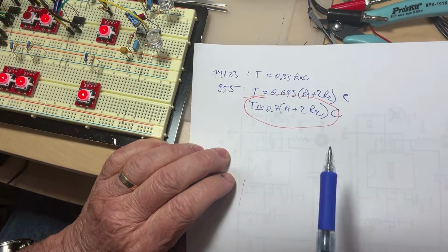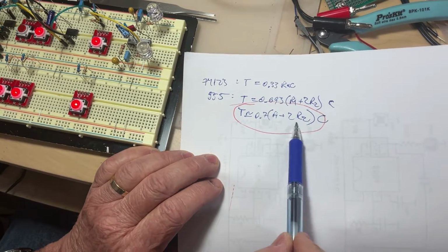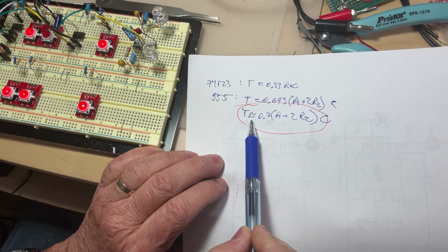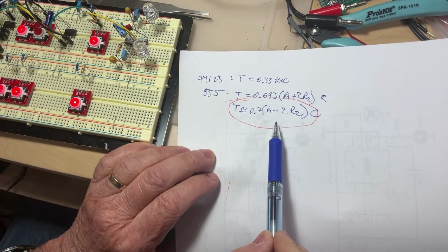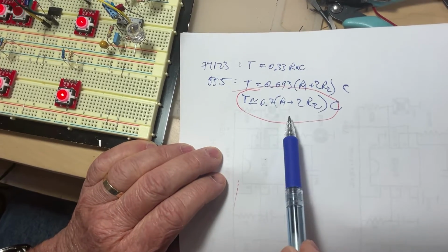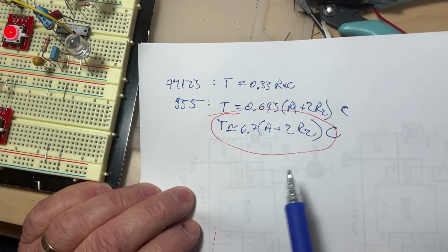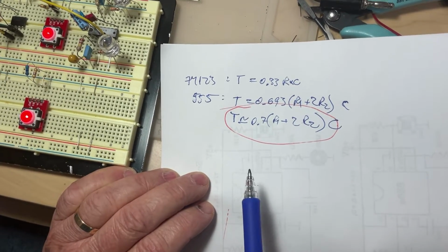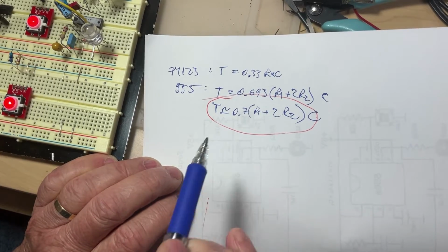Okay? So the purpose of using such a package, exactly like for the 123, is that by only playing with a couple of external components, 2 resistors and 1 capacitor, you can play almost at wish with the duration of the pulse. However, it's recommended that the resistors won't exceed 1 mega. Anyway, because we're going to make these circuits playing only with a couple of seconds to not waste our time, the resistors are going to be surely in the range. Then, this is for the astable circuit.